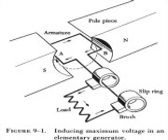This decrease in voltage causes a decrease in field strength, because the current in the field coils decreases in proportion to the decrease in terminal voltage. With a weaker field, the voltage is further decreased. When the load decreases, the output voltage increases accordingly, and a larger current flows in the windings. This action is cumulative, so the output voltage continues to rise to a point called field saturation, after which there is no further increase in output voltage.